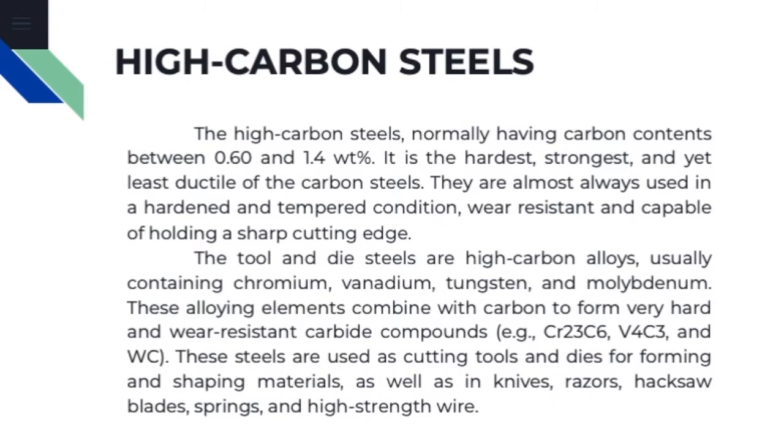High carbon steel. High carbon steel has a carbon content of 0.60 to 1.4 weighted percentage and a manganese content of 0.30 to 0.90 weighted percentage. It has the highest hardness and toughness of the carbon steels and the lowest ductility.